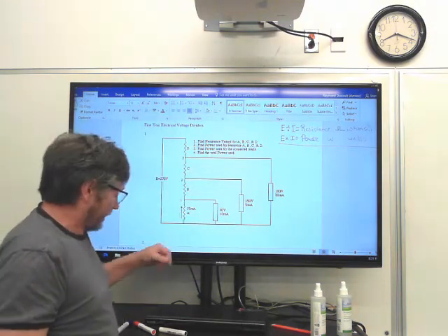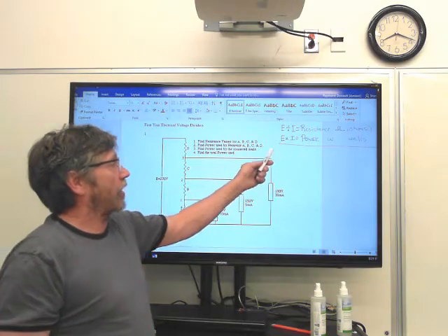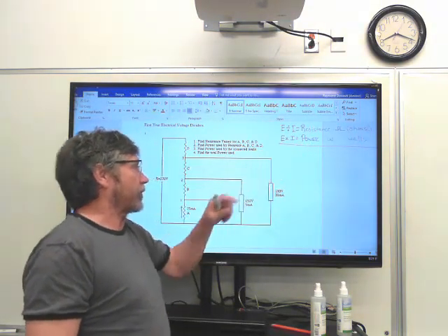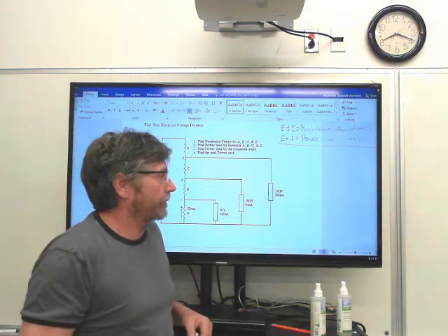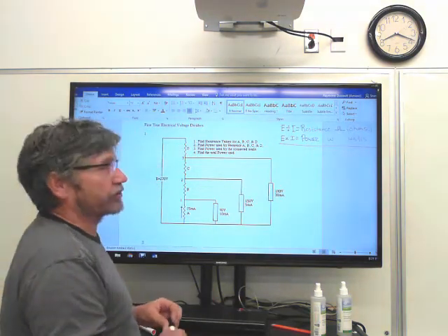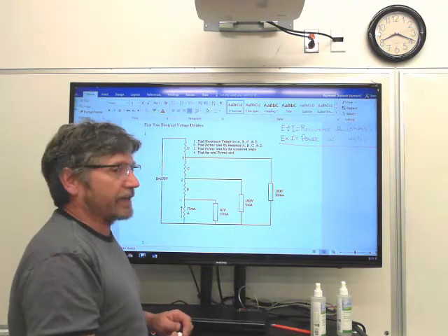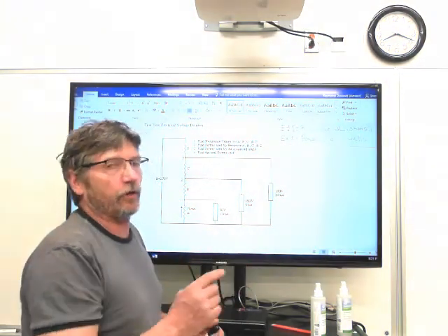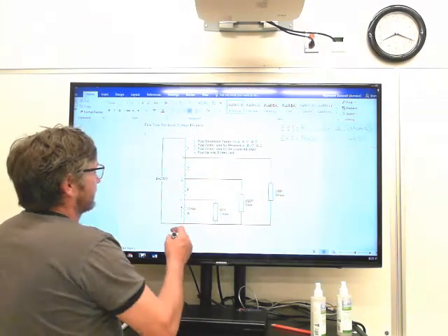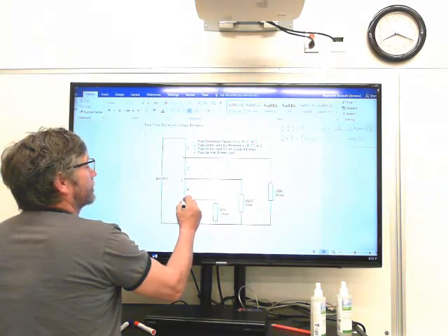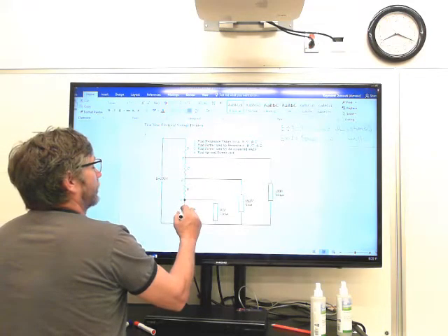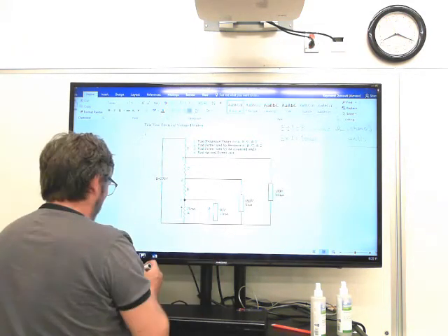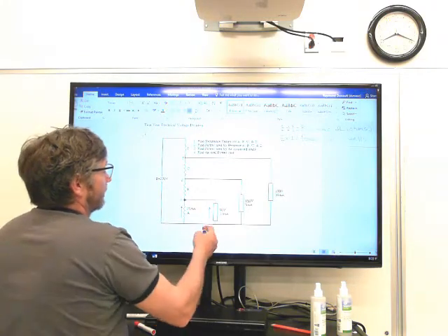So there's the Ohm's law and Watt's law we'll be using later on, but we start off first with Gustav Kirchhoff, starting with his current law. His current law states that the sum of the current entering a node is equal to the sum of the current leaving a node. What that means is this is a node right here where there's more than one path for electron flow. We've got current coming up this way, current coming up that way, and it flows into this